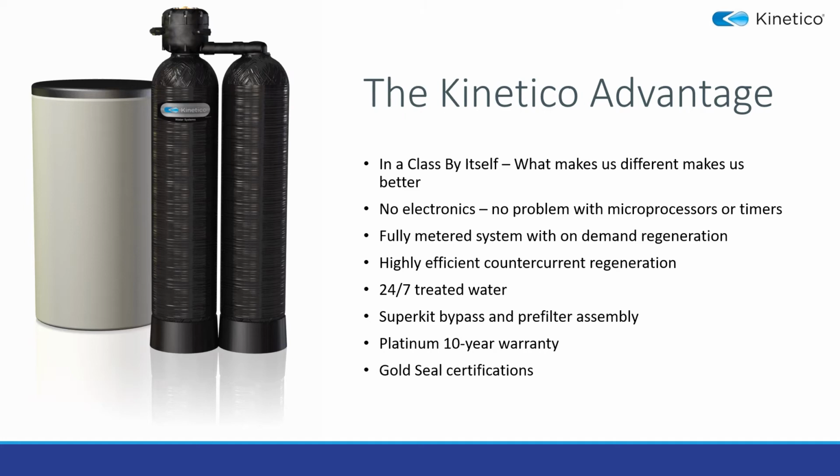In addition to that, single tank units do not provide 24/7 soft water. As the system is regenerating, it will be offline. Any water you use during that period would be hard.